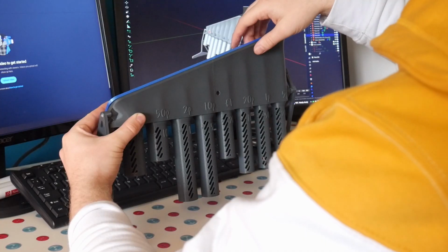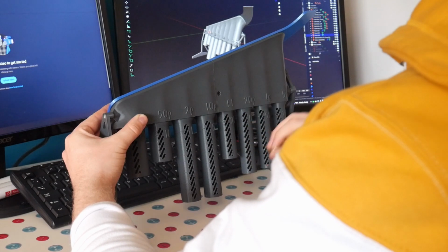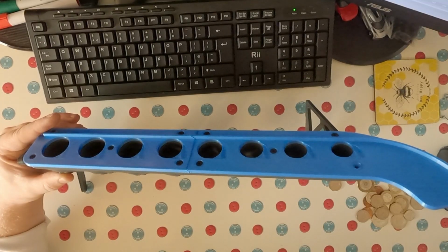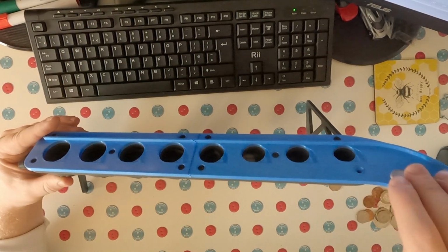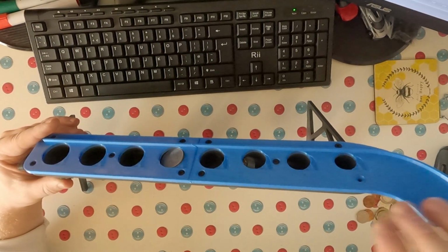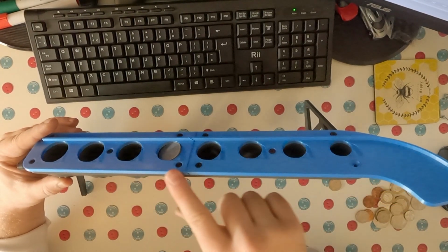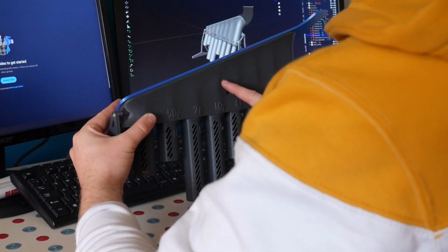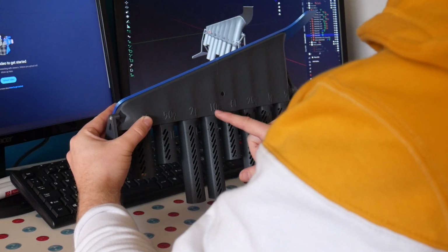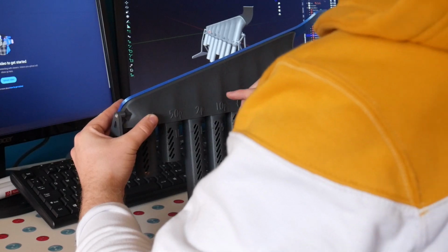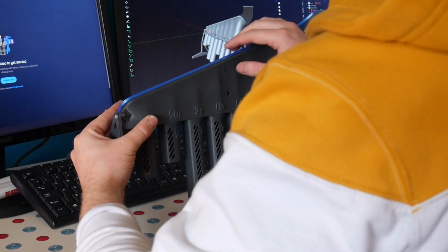But this 1p, my tolerance was just slightly too tight on that one. On some of these they're a little too tight. Ooh. And where it gets stuck, it looks like it goes past this blue plate and gets stuck on the grey piece, and the tolerance really there doesn't need to be that tight. That's just funneling the coins into these holders. So I could really increase the size of these so it doesn't get stuck there.